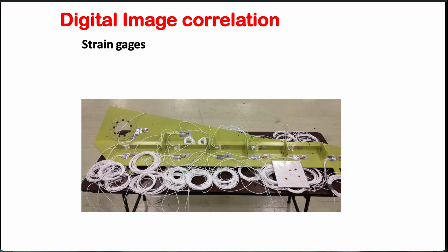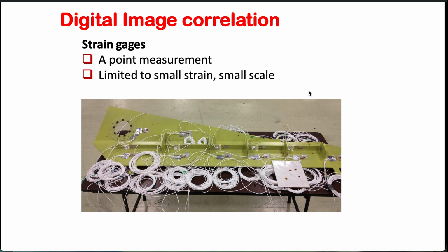our domain. Okay, so if you were to analyze a plate buckling using strain gauges, you have to install strain gauges at every location. And then for the locations in the middle, you have to interpolate your results. Again, not a very accurate representation of the field of strain that we want to see on our plates. Okay.